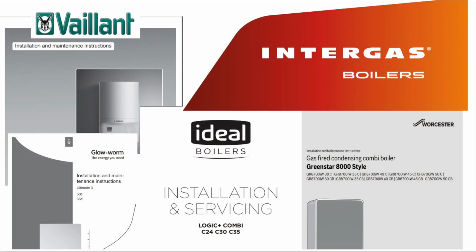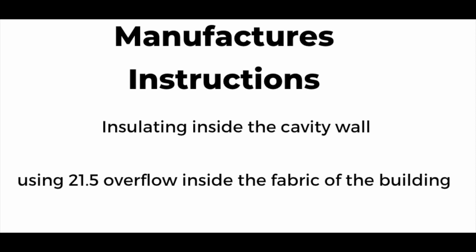So some differences we found in some of the manufacturer's instructions that aren't in the British Standards. One would be insulating inside a cavity wall. Now obviously this doesn't need to be UV protected because it's inside the cavity, so you can use standard insulation for that. Some manufacturers are allowing us to use the 21.5 overflow, but the transition must be inside the fabric of the building, using a 21.5 to 32mm reducer.